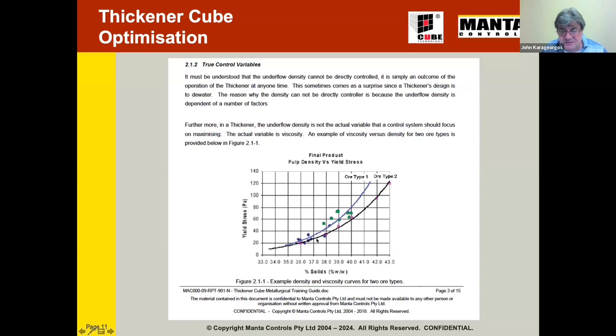There's a lot of data down here, and then only a few data points where we're doing test work, pushing the density up, increasing viscosity, having pumping issues. We're lucky in this plant to have hot process water to try to change the rheology to be able to pump. So these are really important: sizings and understanding your rheology curves.